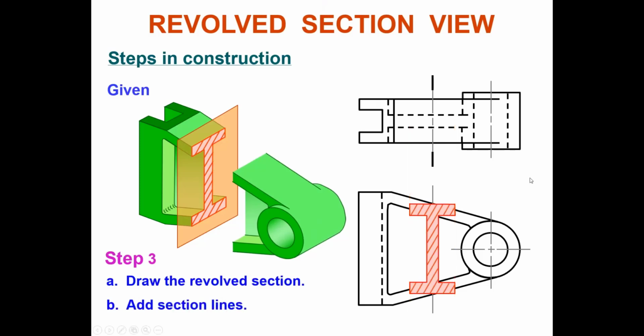Faham guys? Ini nama dia. Okay, this ni memorize guys. Question in test, they give you these two orthographic views, front, top and front. Dia cakap, what type of section? Boleh faham tak kelas? Boleh differentiate what is full section, what is half section, what is offset section, what is broken out section, what is revolve section.